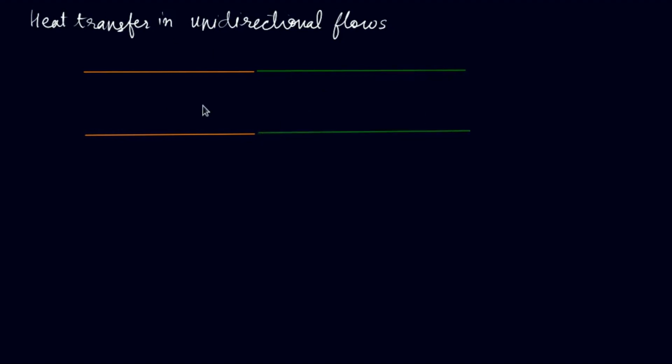We consider the heat transfer in a fully developed laminar unidirectional flow of a Newtonian fluid through a straight circular tube. In this particular geometry, we have an insulated section in which the incoming flow has a Poiseuille profile.